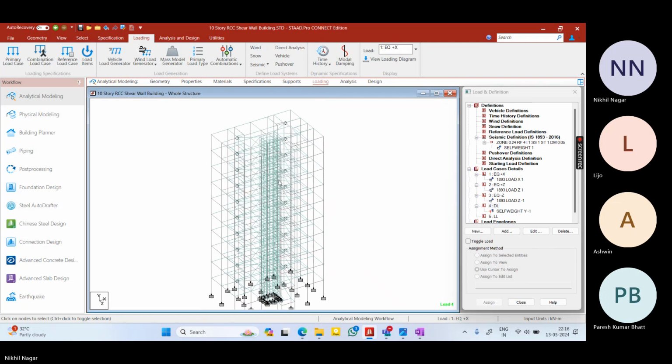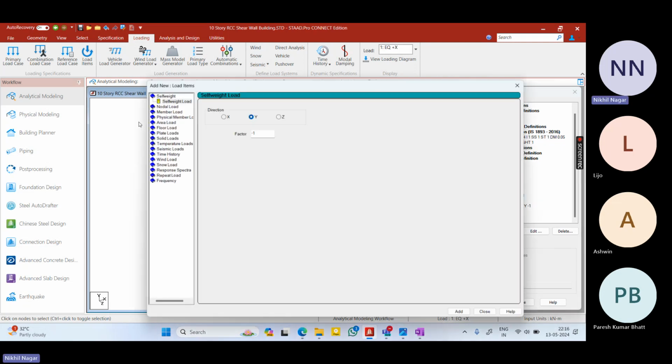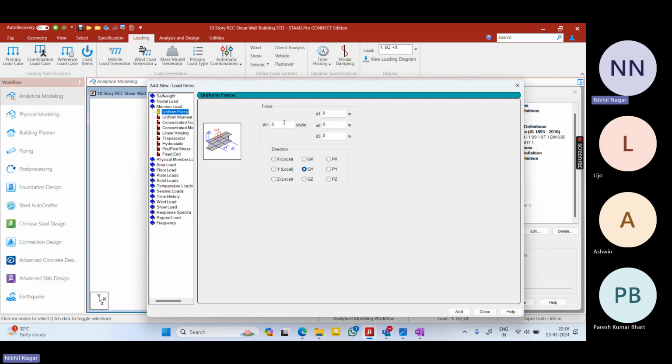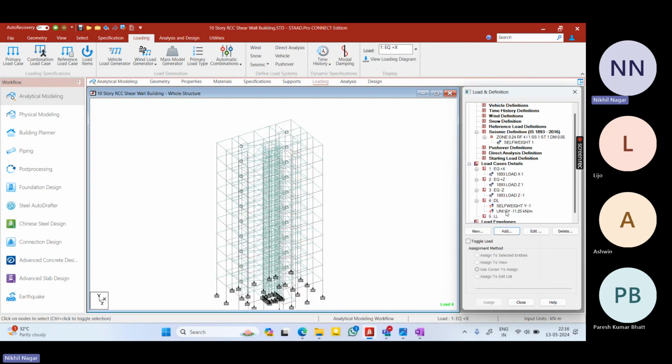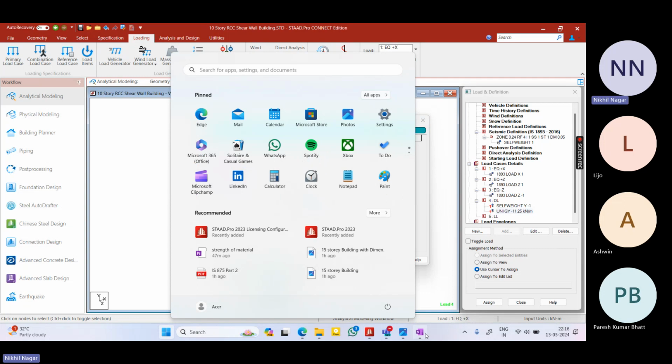Now the dead loads are first our self-weight. So dead load is our self-weight first. Now we have to take the dead load of our walls. That came out as 11.25, which we calculated in the last lectures. For the parapet wall, that will come out as I think 1.2 and 2.5. In this case, we have changed the size of the beam section, because at that time I had taken the depth of the beam as 500 mm. So we have to calculate it again.